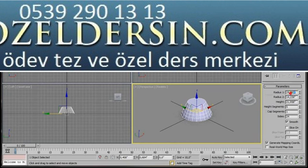Now here in Radius 1, we'll type in 18. Radius 2, type in 10. Height, we'll type in 15. Our height segments, we'll bring them back to 1. Cap segments, we'll just leave them at 1. And inside, we'll just type in 32.